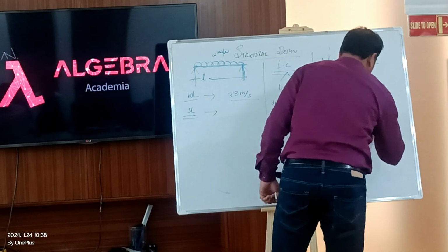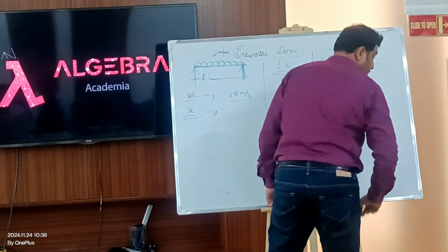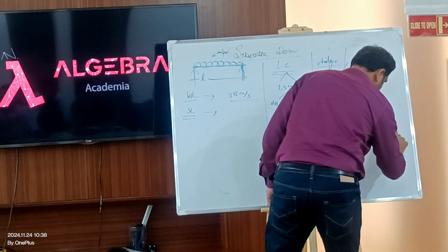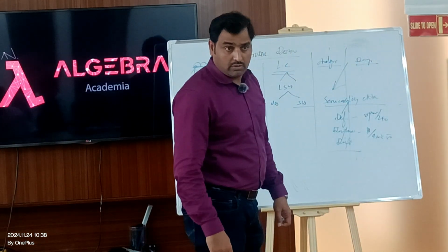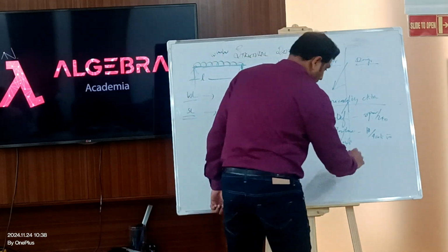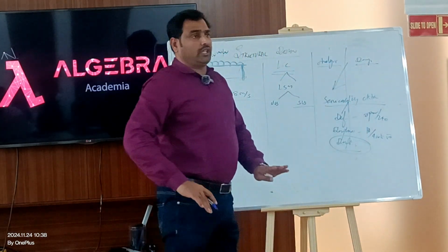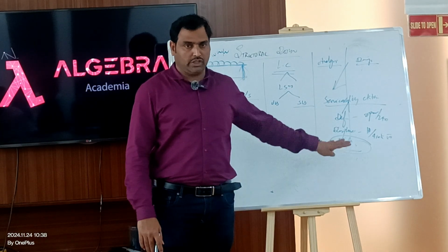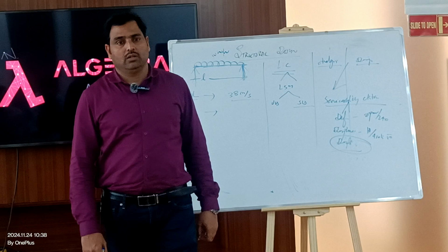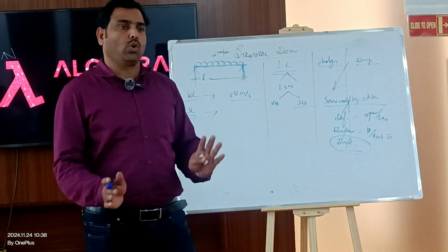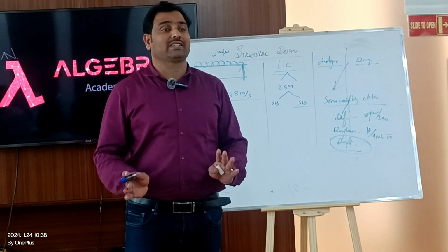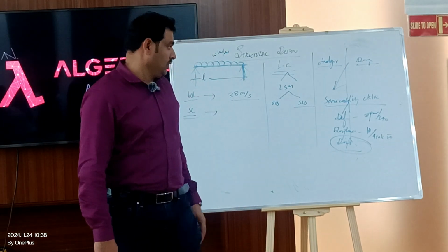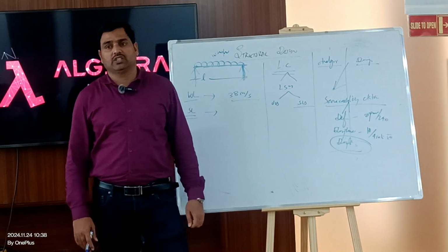Now, what is the allowable limit? Span by 240, h by 450 to 500. Okay. I don't want to confuse you. Interstory drift is 20 millimeter, which we will discuss while going to the model. While going to the model, I can show you the allowable drift as per codal recommendation, how to calculate, and what the DBC criteria is, how to calculate. I don't want to give you the rough figure here. But take these two: deflection and displacement.